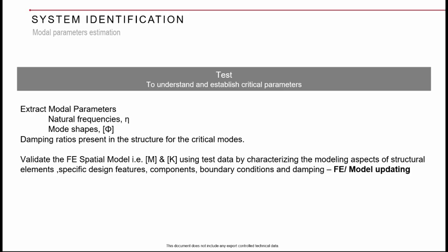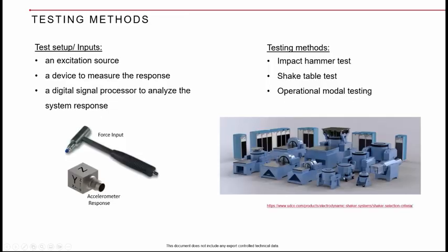I mean, fine tuning by comparing your analysis results with the test data: what is the difference between my analysis natural frequencies and the test natural frequencies, how the mode shapes correlate, how the frequencies correlate. Then the damping is only a parameter from the test which will key into the analysis to compare the responses again. So in this process, whatever assumptions we made ahead in the analysis, when we revisit and update or fine tune all those assumptions, that is called model updating. We'll come back to this again later in detail.